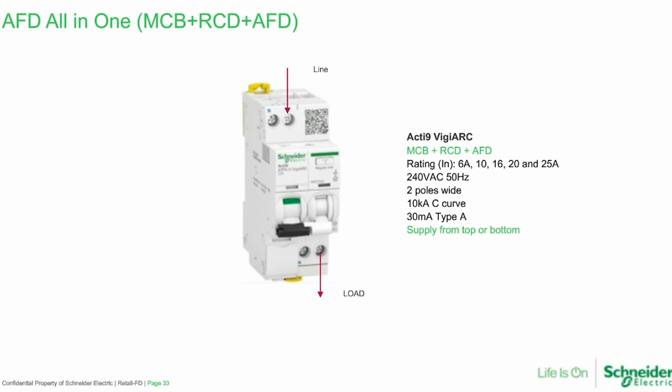So it does have some implication on your installations and designs, but it's not practical with current components and current technology to be able to get this type of all-in-one technology into an 18mm wide device. As you can imagine, RCDs are already jam-packed with lots of components to do the MCB and the RCD, and we've come along and put extra components in there for the AFDD section. So we've had to go with this form factor and this format. It is targeted for single-phase circuits, and 6, 10, 16, 20 and 25 amp is what it's available in, and the people protection RCD setting is at 30 milliamps.